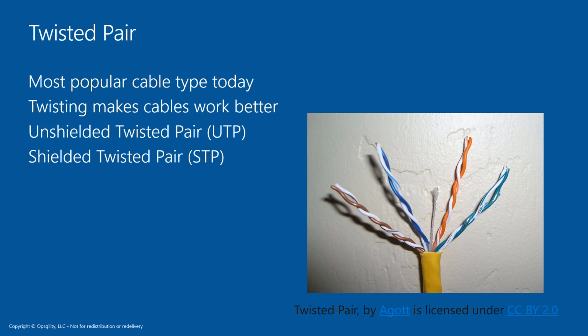Another addition you can add to your twisted pair cable is the plenum option. Plenum doesn't actually make cables work any better. They just add additional costs to both UTP or STP, but are required in certain types and sizes of buildings. So if you have a fire, you're going to want to have plenum cables because the toxic plastic as it's melting in the non-plenum cables can actually be very hazardous to your health.